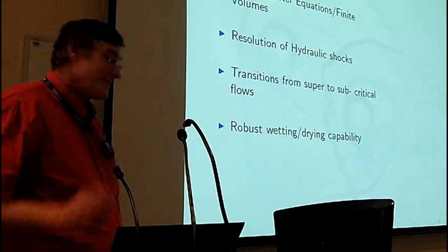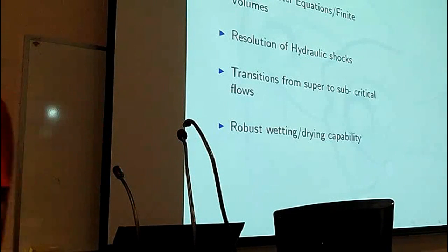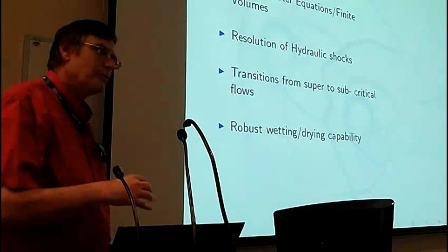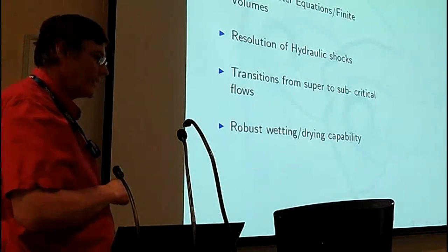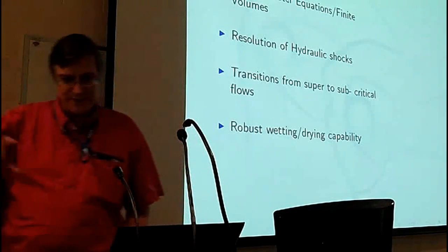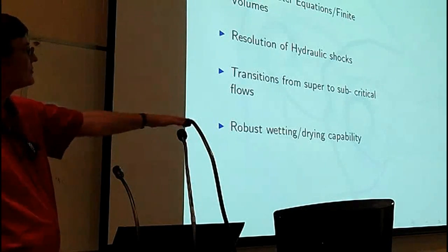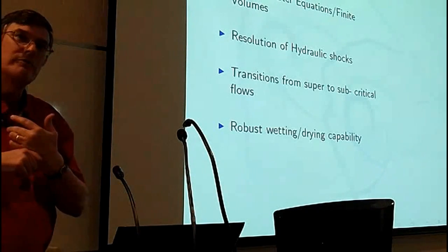So, what can it do? Well, what is it? There's a very precise model of fluid flow called the Navier-Stokes equations. If you average them in depth, you get the shallow water wave equations. And so, if your water flow is seen to be very shallow relative to the extent in which you're interested in, then the shallow water wave equation is generally a pretty good model for that.